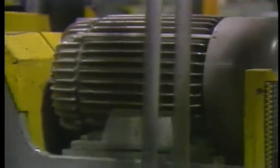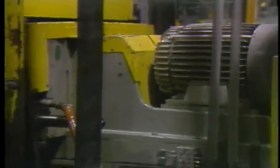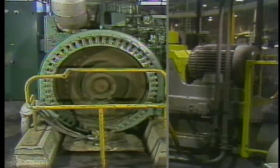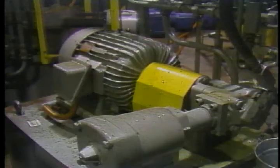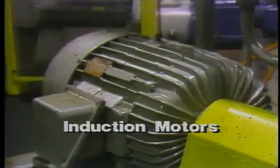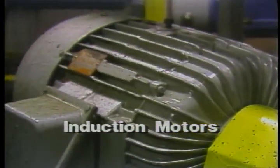Now there are 2 basic types of single-phase and 3-phase AC motors: induction motors and synchronous motors. They differ in the way the rotor poles are produced. In induction motors, the rotor poles are the result of currents induced in rotor conductors.